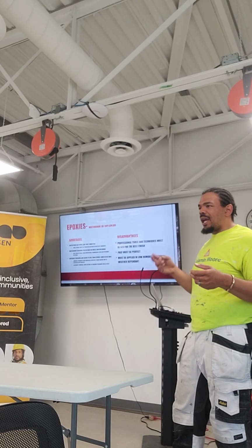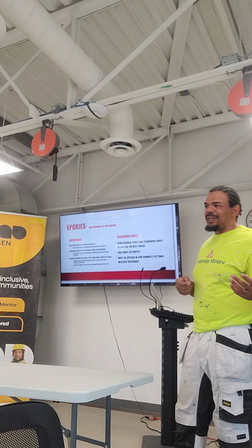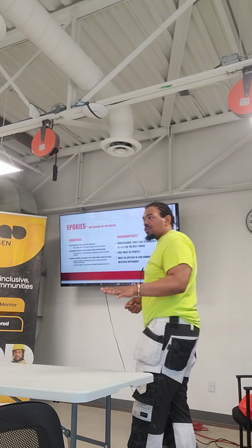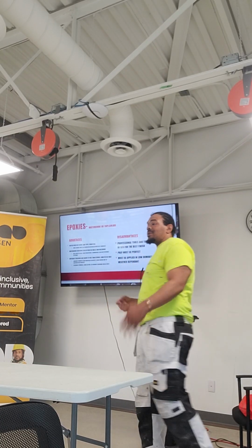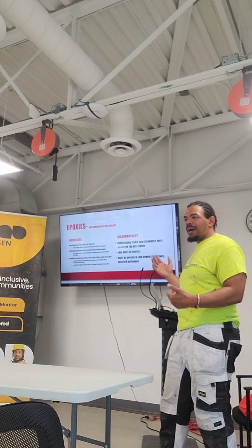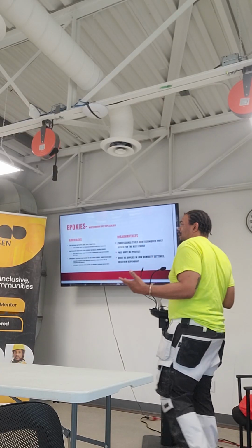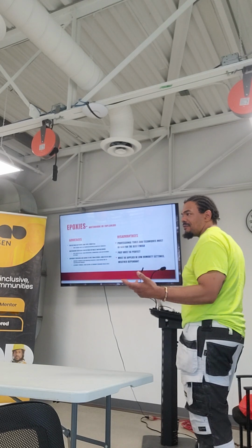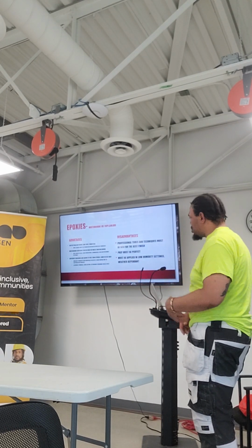Acetone and lacquer thinner dry extremely fast, but acetone is not as toxic. The difference is acetone is also not as astringent, so it won't do as well at cleaning and pulling up dust and dirt. So that's the reason we prefer to use lacquer thinner as part of our epoxy prep. Some people don't. I don't see how they do it that way. I do it the way I do it. That's the way I was trained, that's the way I learned to do it, and I haven't had failures yet. So that's the reason why I prefer that method. But you can do it in any setting.